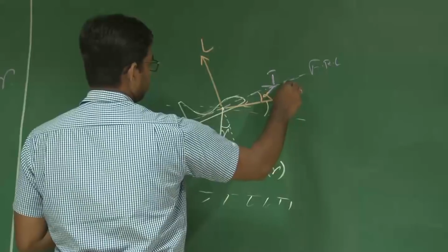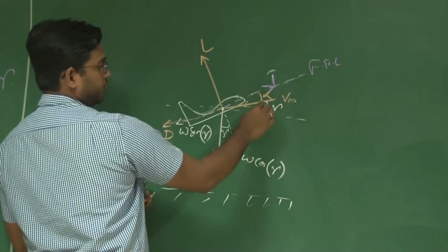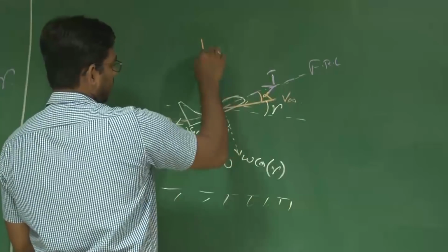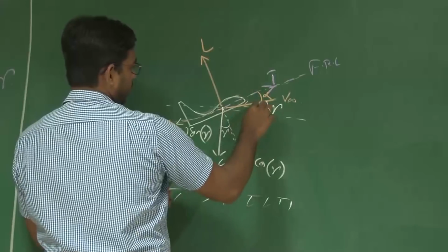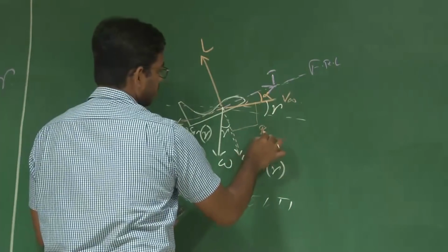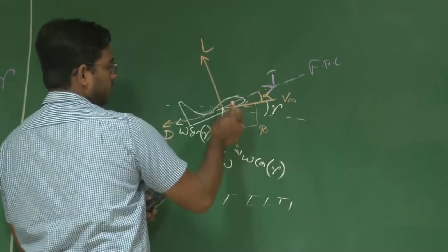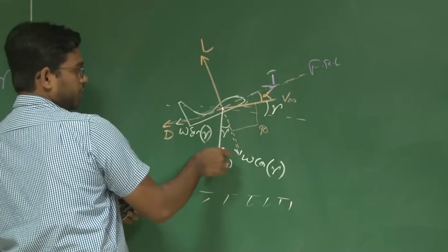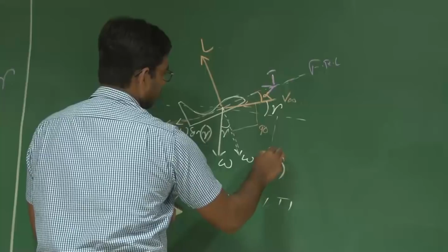We know V infinity and this negative lift line are perpendicular. So we know this angle is 90 degrees. So you have this as gamma. This is your local horizontal, and weight acts perpendicular to local horizontal. So this angle is 90 degrees again.